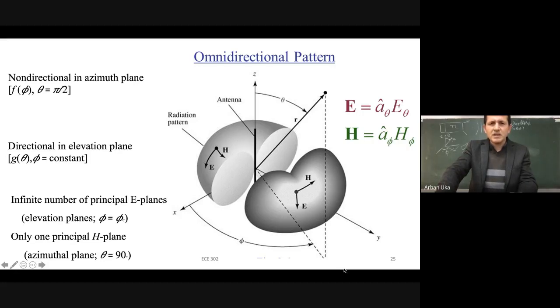Now, as we are discussing, this is an omnidirectional antenna, and far away from the source, the projection of the E field along E_r is 0. We're assuming that E_theta has an electric field with a projection only tangent to this donut-shaped distribution. If you consider this a donut-shaped distribution, E_theta is tangent, pointing along the direction where theta is increasing. The magnetic field is again pointing in the direction tangent to this donut-shaped power distribution, with an angle phi.